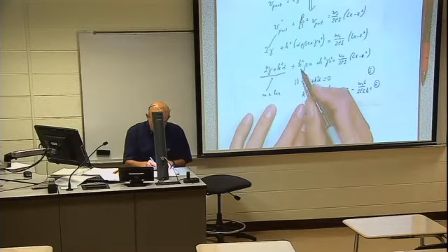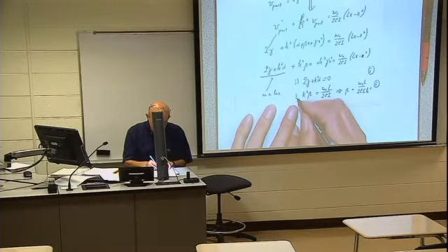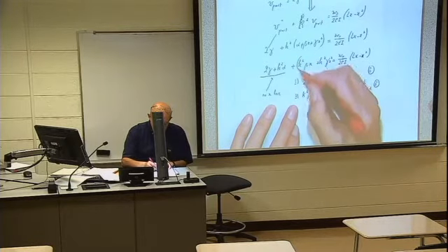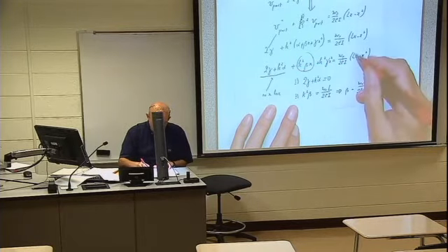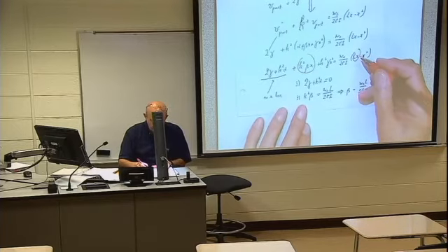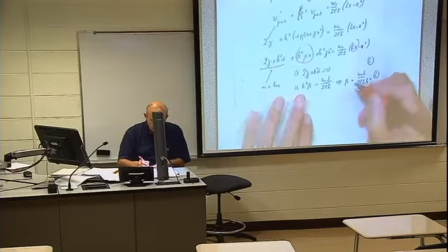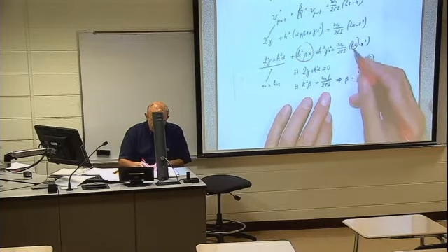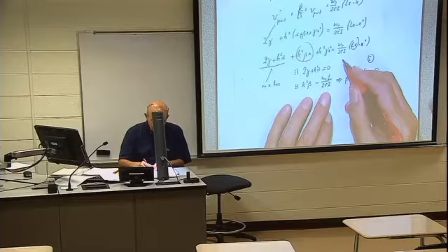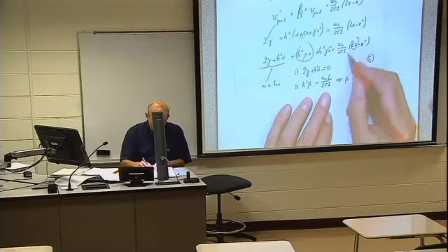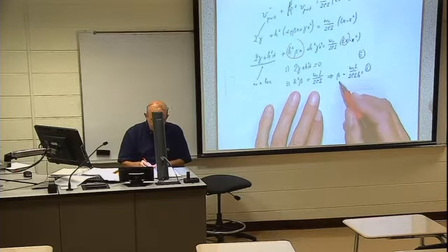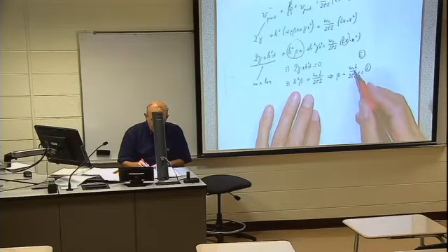Second equation, k squared beta, that is this term, must equal this term. That is this second, equals W0L over 2EI. Coefficient in front of x must be 0. So from the second equation, I get beta. Beta equals W0L over 2EI k squared.